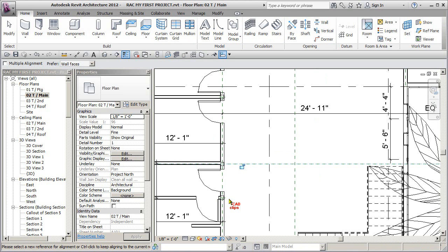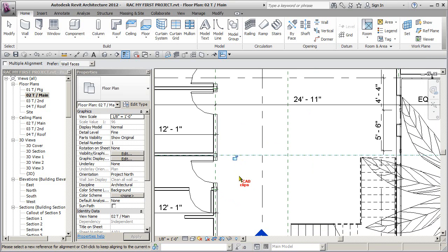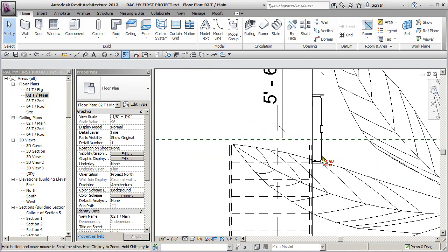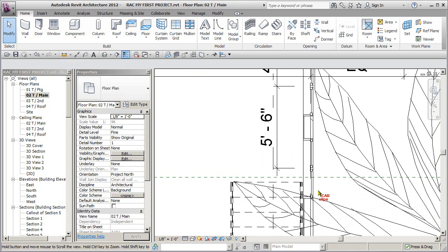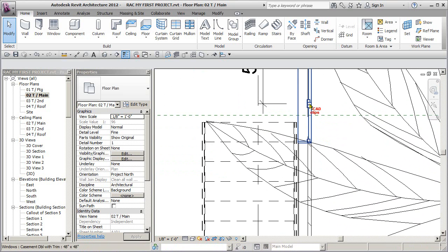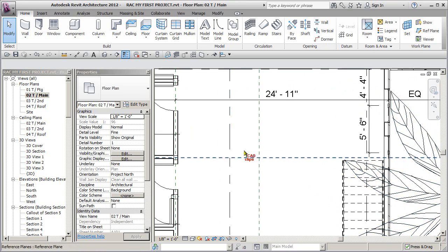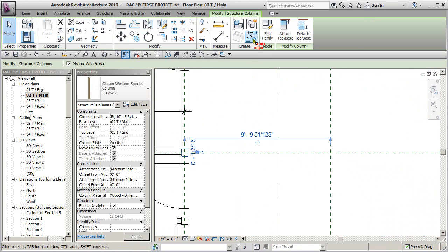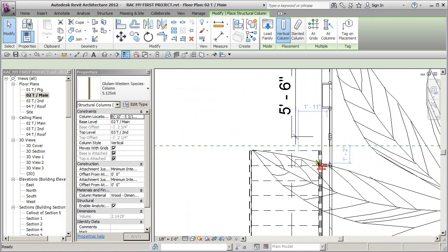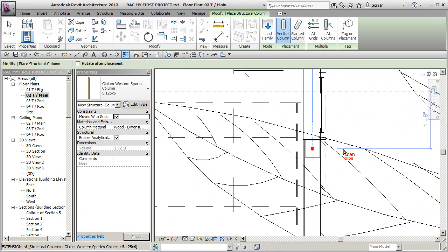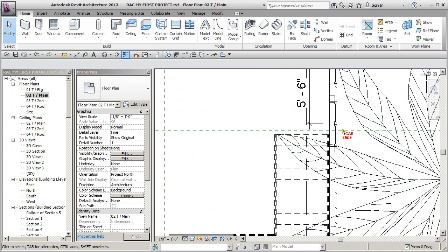Okay. Now I have a beam running under there anyway, picking up the joist. So then that's just going to be a point load. I don't know. Do I need a post under there or not? Maybe I do. Over here, are we in the middle of a window? We are in the middle of a window, so we're going to have to put a header in there and transfer that over to a couple of posts. So we could end up taking this post and say create similar, and inevitably we'll end up with a post on each side of these windows here.